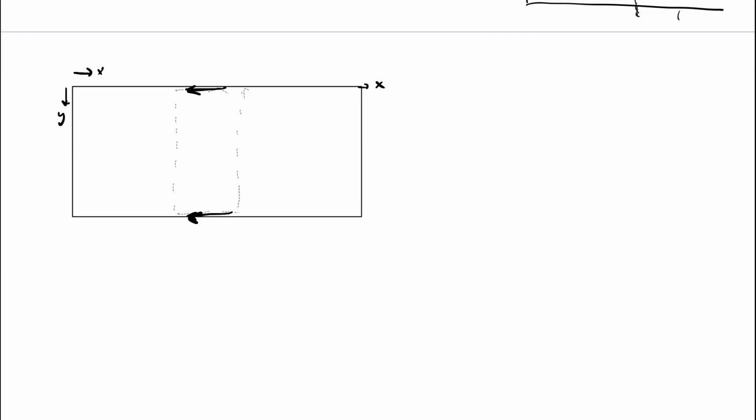If I just call this shear stress tau s, the full force is tau s times the perimeter of the duct times dx. That gives me the force without even needing to go into the detail of doing a control volume on dx and dy, right? I'm just calling the effects of the y velocity gradient tau s, and I'm kind of punting it to that model. So if I do that, then I can just do the control volume in its entirety this way.